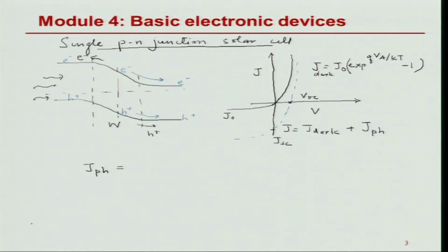Each photon will be responsible for one electron hole pair for linear processes, and from the surface this is going to go down exponentially, because we know that the way light gets absorbed in a material is given by, if the intensity here is I naught, the absorption coefficient of the material. So electron holes are getting generated more here, and as you go deeper in, less of them are getting generated.